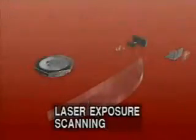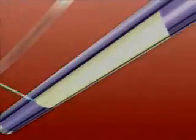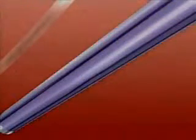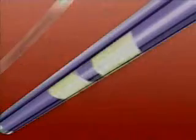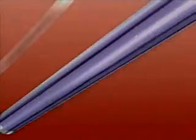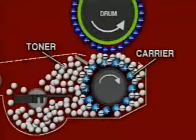In the laser exposure scanning process, the laser diodes are turned either on or off, depending on the image signals. The electric potential of the drum surface where the laser beam is directed gets close to 0 volts, and the potential of the drum surface where the laser beam is not directed remains at -600 volts. As a result, a latent image, which cannot be seen directly by the human eye, is formed on the drum surface. In the development process, the new type dual component development process is adopted.